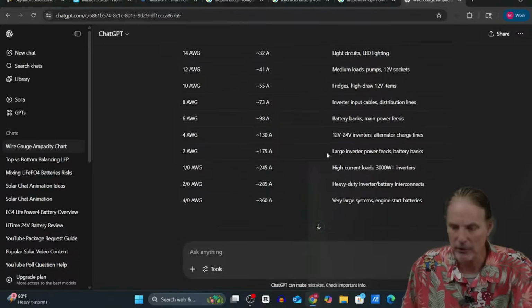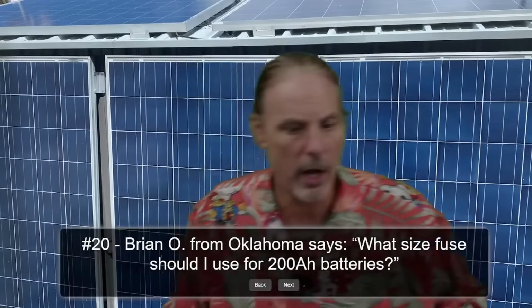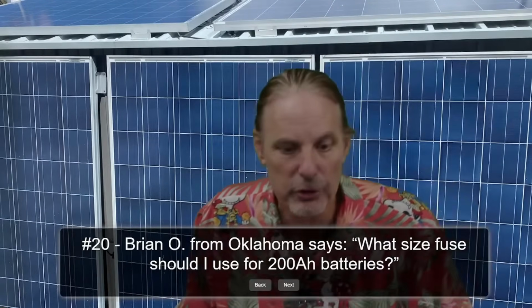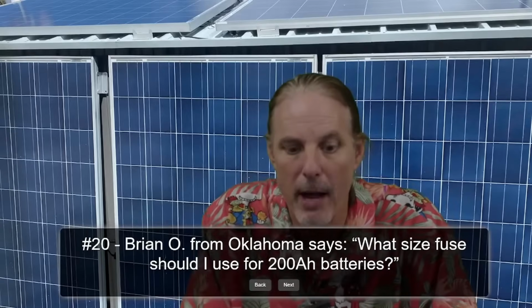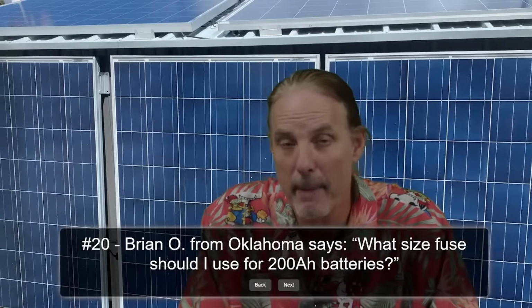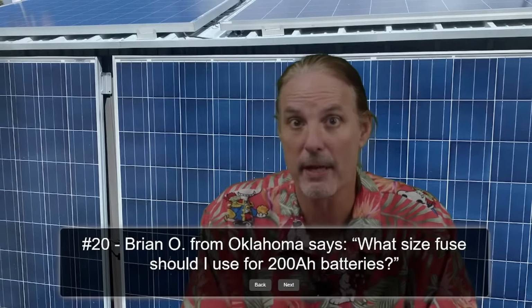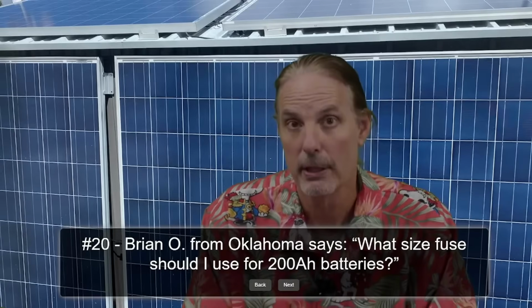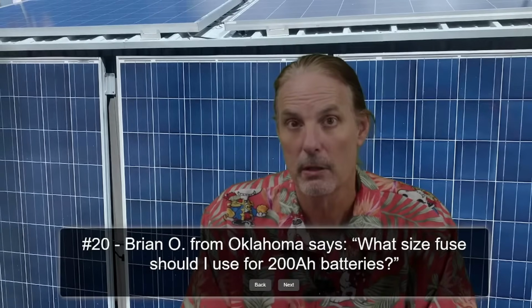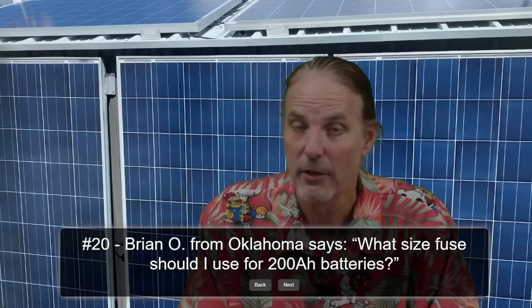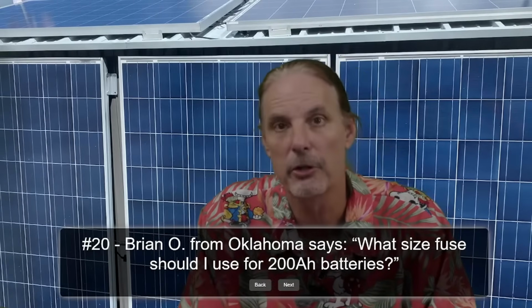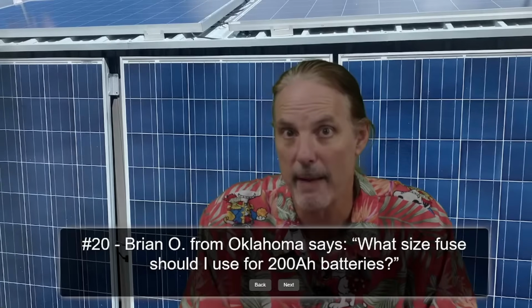So we go back to the original question, if I can find it. And the original question was, what size fuse do I use for a 200 amp hour battery? Well, if the 200 amp hour battery also has a 200 amp BMS and the wire can support it, then you would put in a 250 amp fuse.